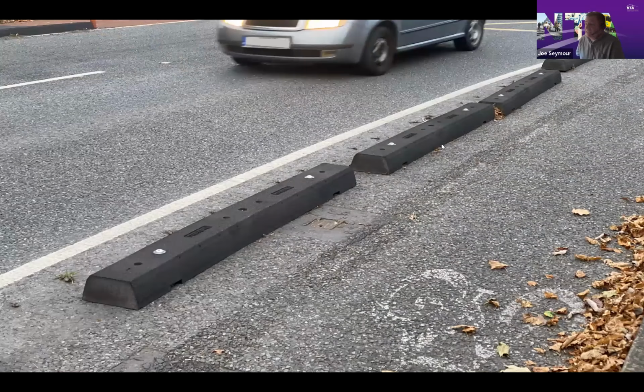This is a scheme that's been in place a couple of years now, and you can see that the rubber curbs have moved. You can just about see the screws are left in the ground, which could be a hazard to other vehicles running over them. They need to be inspected fairly often and reattached to the ground as necessary. I have seen these ones in particular across the cycle track as well, which may not be that visible at night, so it could be a hazard.